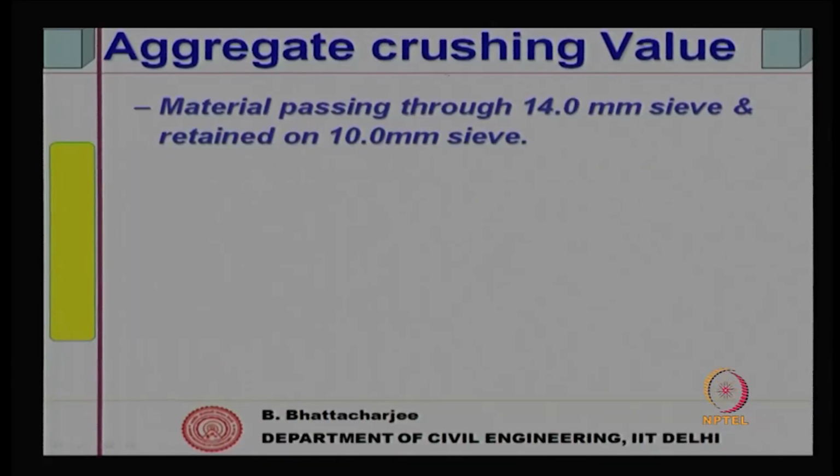Okay, now, the properties of aggregates. The strength of aggregate is measured through the aggregate crushing value, because parent rock strength is usually not relevant in the case of concrete. Once you fracture the parent rock, its strength would be higher, because fracture has already taken place through the fracture planes. So, whatever is remaining must be stronger. Well, there is a size effect: the larger the size, the probability of finding a failure plane or fracture plane is more. Therefore, there is no point using rock strength for aggregate.